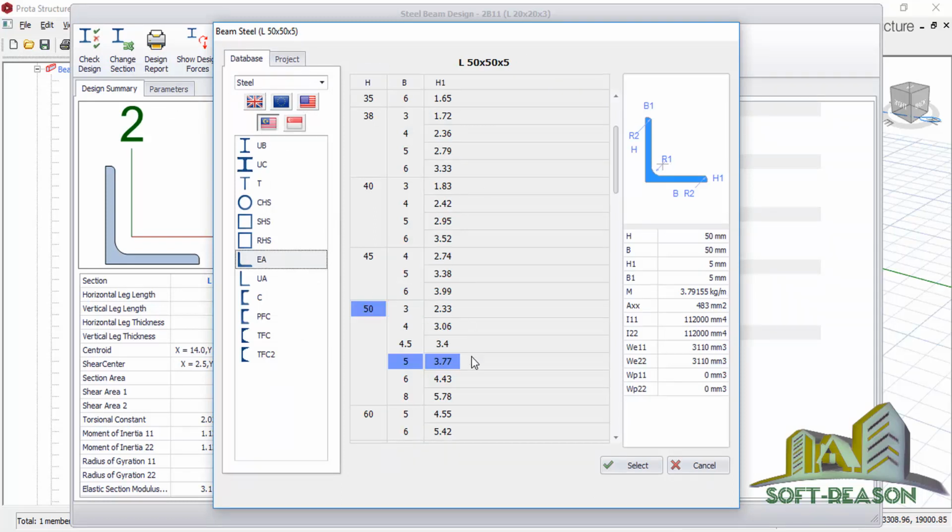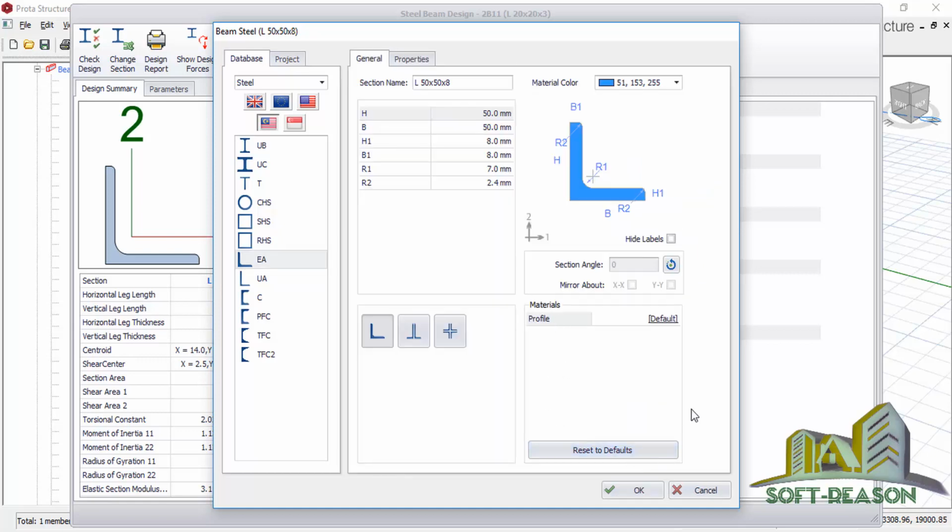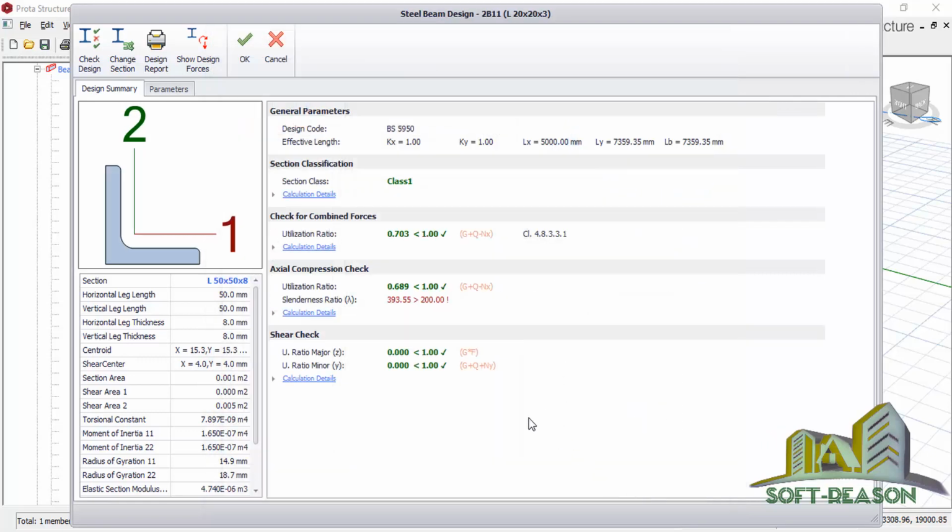We are going to consider this before going to 60. So you click on this. All right, so you can see it has passed the design. But the slenderness check, slenderness ratio, is still giving some warning. Because actually this is not supposed to be slender as expected. It's just because we have not divided the braces into two. That is why it seems slender.